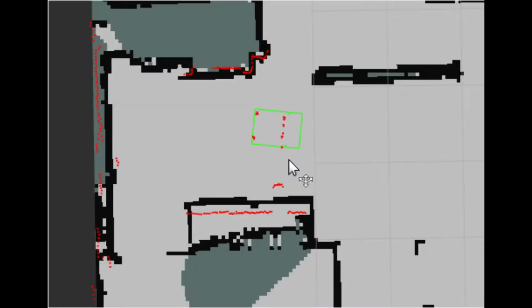The software driver for this little LiDAR does have a cut angle, so I'm able to cut out one section of the scan that I don't want reported and misinterpreted, but you can see that I actually need to cut out 3 sections where I'm going to get these hits that are within the robot's footprint. Those may or may not be a problem, but I find them annoying at the very least.